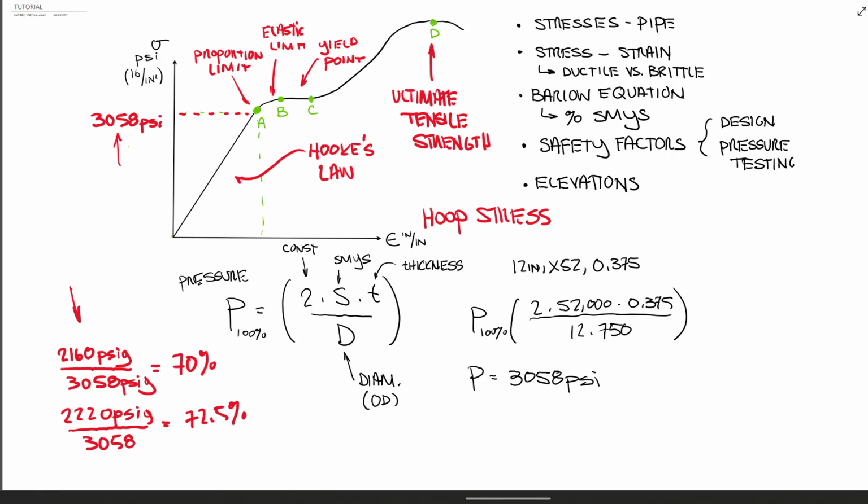Well, most of the new piping that we put in, we always design for the highest, 1440 is typically what we do. 1440 is pretty much the max that a class 600 flange system can withstand. So we pressure test all of our pipe and design it for 1440. That's not always the case, but for new installations, more often than not, we're going to shoot for a maximum design of 1440. So it doesn't have to be that.